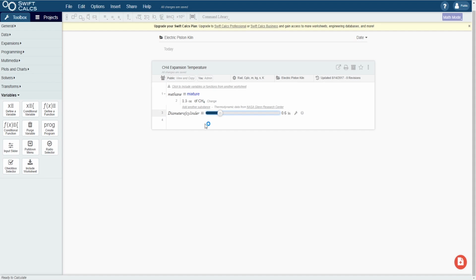And we have the interior form, which is going to have all the ridges on the walls to put the resistance wire in. And then we have the door former, which is also a permanent cast, going to be made out of steel. Thin steel, with thin gauge on the side and thick gauge on the outside, going all the way around, and then we're going to pour into that.